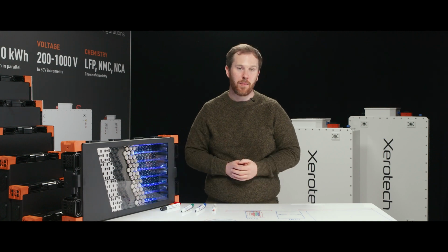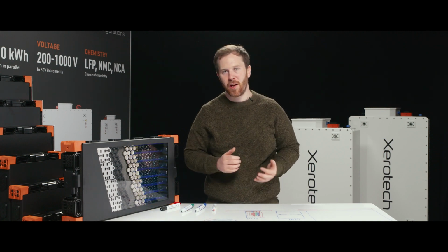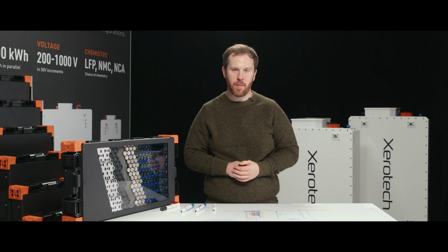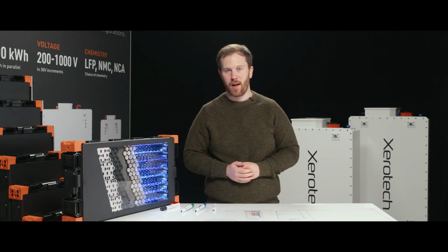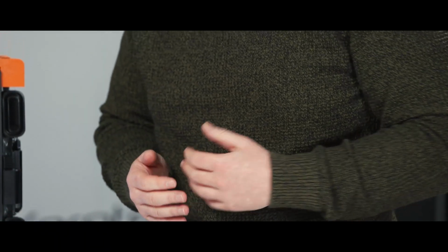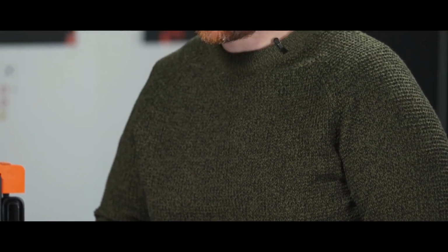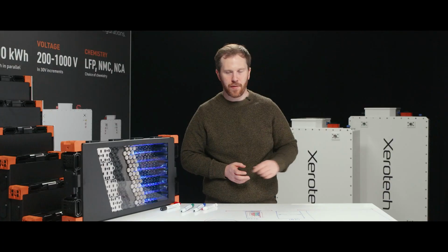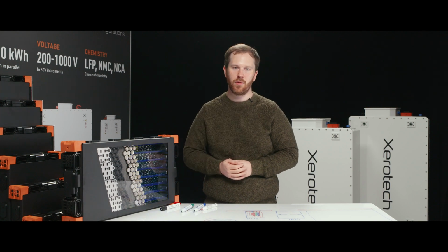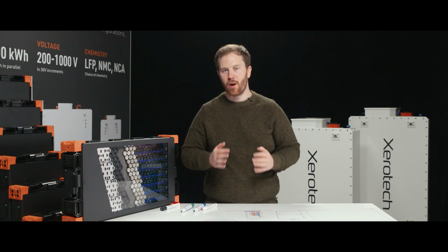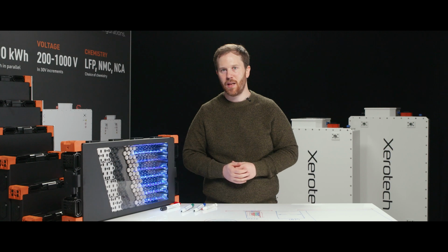Thermal management is incredibly important for a lot of future applications, especially hybrids, which are going to be a big thing for heavy-duty industrial vehicles that are going diesel electric, as well as full BEV, and also high-performance vehicles that generate a lot of heat. You must have strong thermal management for these, or it can result in a safety risk, because if you keep discharging on these cells, their temperature will just keep climbing. And if it reaches a certain threshold for some chemistries, they can go on fire. So thermal management is very important to maintain the safety of the battery.